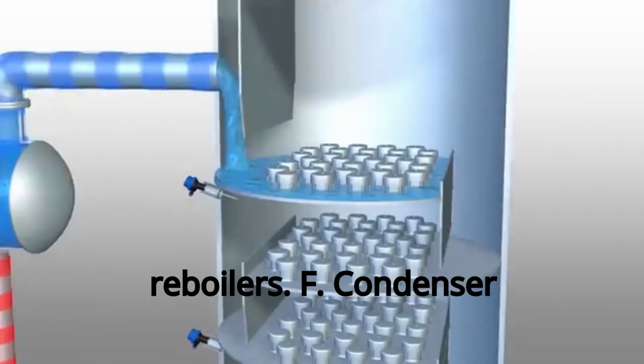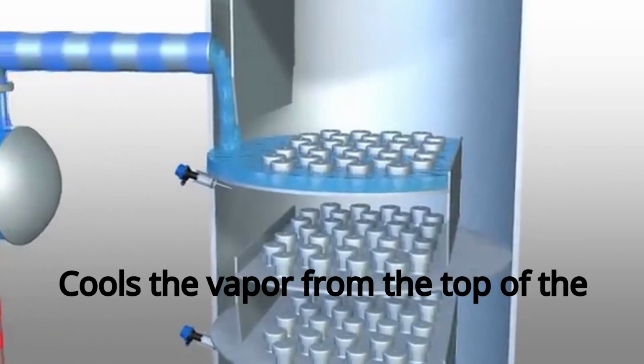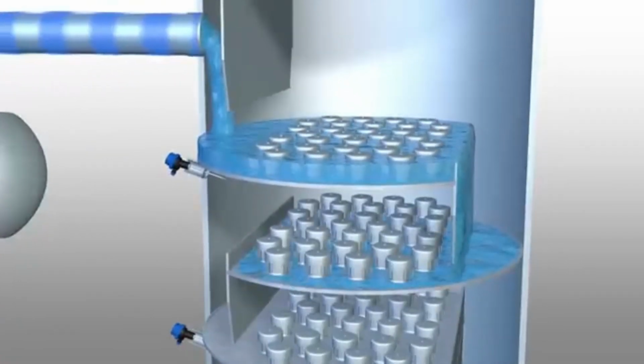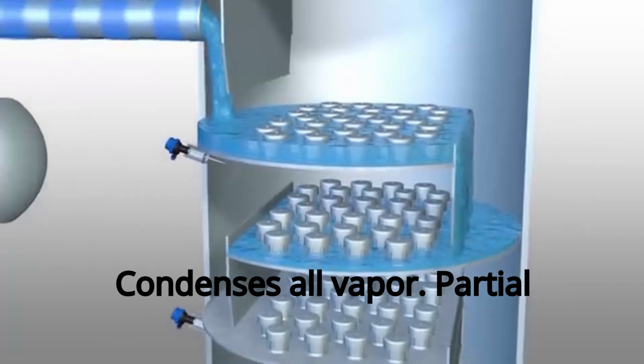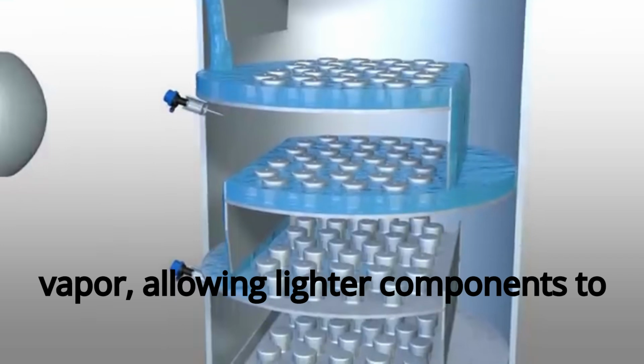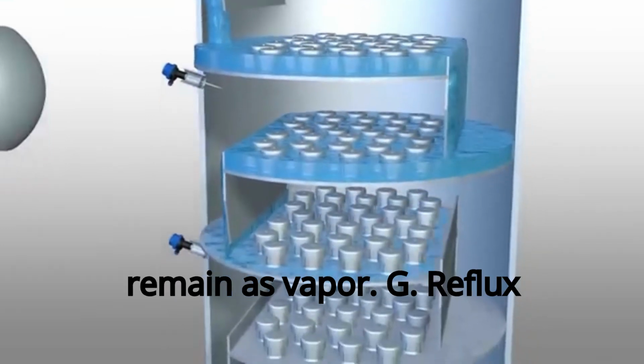F. Condenser, cools the vapor from the top of the column, converting it back into liquid. Types: total condenser, condenses all vapor. Partial condenser, condenses only part of the vapor, allowing lighter components to remain as vapor.